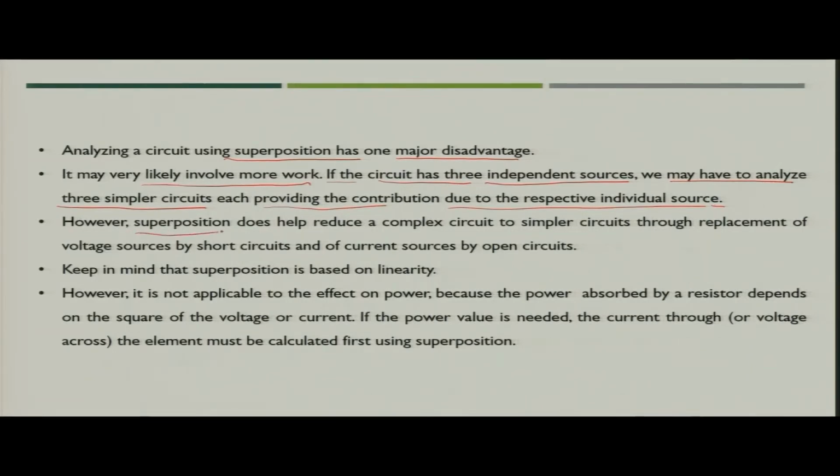But the important thing is that it helps us reduce a very complex circuit to a very simple circuit, because you are replacing the voltage source by a short circuit and the current source by an open circuit. So, using the superposition theorem, although you are analyzing multiple circuits by taking one voltage source or one current source at a time, eventually you may get the solution very early, because the circuits are now simpler as compared to analyzing the circuit with multiple sources connected.